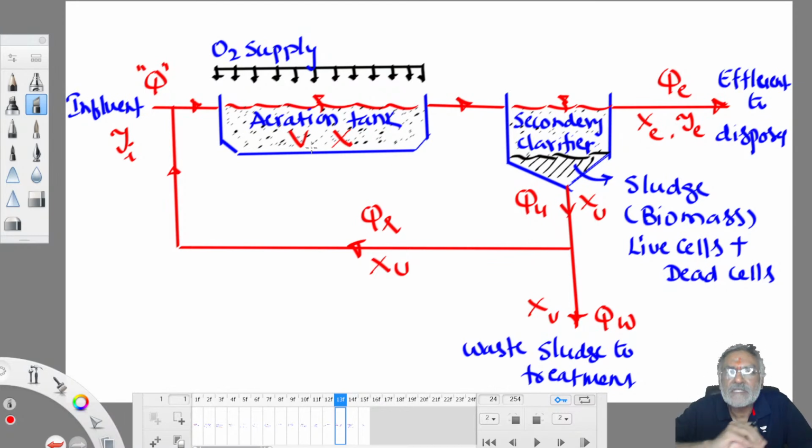Therefore, a portion of the sludge is sufficient. If you take the entire sludge, again you can't meet their demand. That much food is not available in the aeration tank, and again they will die. So that is not good. Organisms should not die, they should remain active. That's why it's called the activated sludge process. Understood now? Arjun?